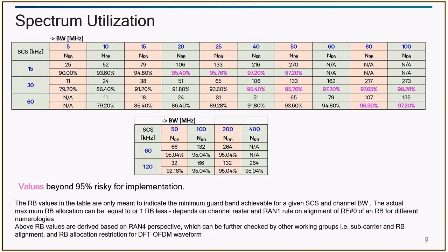but at different frequency locations to avoid interference. And also, Ashok, when you boot up, we don't know what is the bandwidth of the network. Correct. So you always assume some center frequency. No, you would come to an LTE band. I'm talking of standalone only. In case of standalone, yes. So we don't know, right? Is it 100 megahertz, 500 megahertz, we don't know.